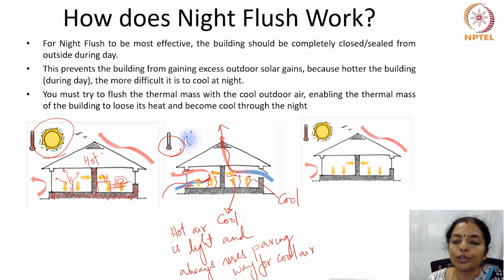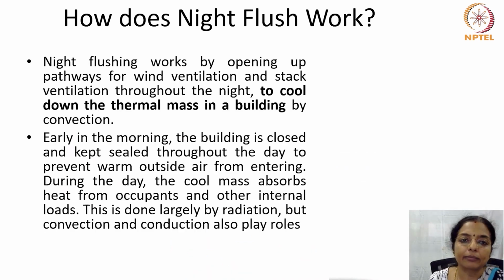At that time, what should you do? You should close all the openings. So the inside remains cool during the day, and in the evening again, as the people and the contraptions would have radiated heat, the indoors become warm. Again open the window at night and continue this cycle.